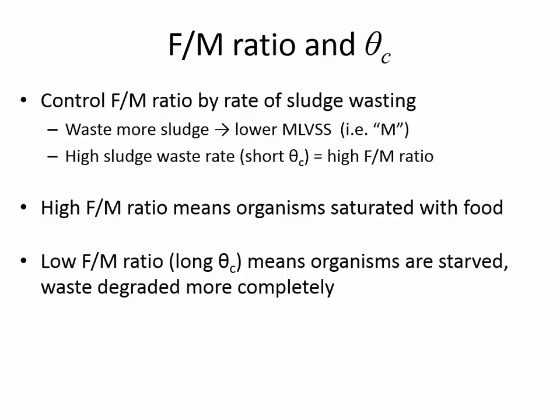If you have a low F to M ratio, the bacteria are doing something similar. They're not just breaking down the simple carbohydrates, they're finding every possible little scrap of energy that can be broken down in that wastewater, being more efficient and degrading the waste more completely. What corresponds to a low F to M ratio is if the cells are in that recycle system a long time. A long mean cell residence time might be as long as 10 or 15 days that the average cell is spending in the secondary treatment.